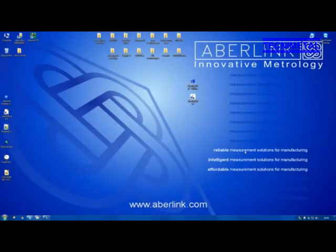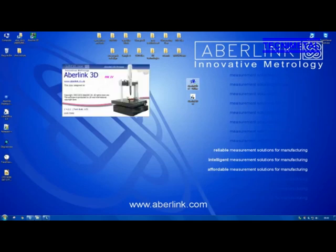Okay, first of all we're going to choose which icon to run from. So you can see on the screen we have an Aberlink 3D v4 icon and an Aberlink 3D v4 offline icon. Now the Aberlink 3D v4 will try to start the machine and look for the various motion control devices. To program offline we need to choose the offline icon.